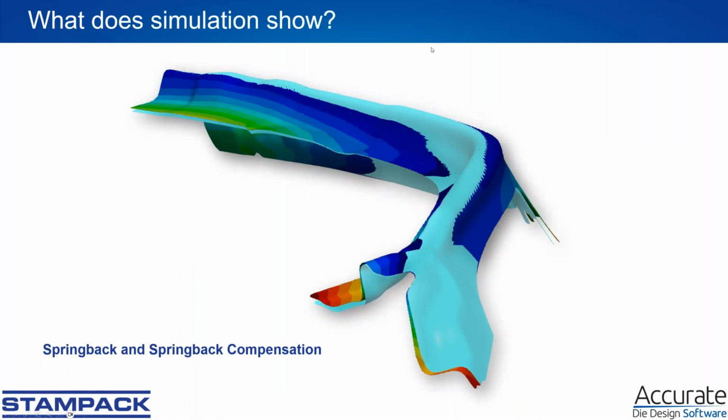Very much connected to this, and I think this is also everybody's problem, is springback, because springback is a typical thing that drives you out of the tolerance. And so Stampack predicts springback for you, and Stampack compensates the die surfaces so that you can come back to tolerance. And later on, I have an example for you so that you can get a feeling for what springback compensation does.